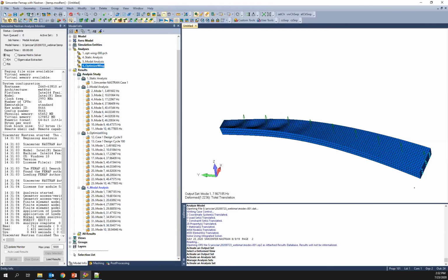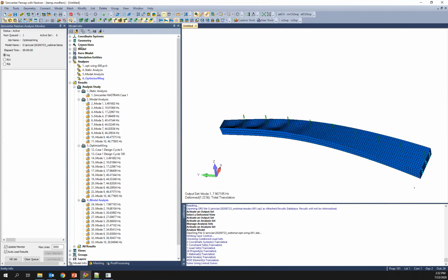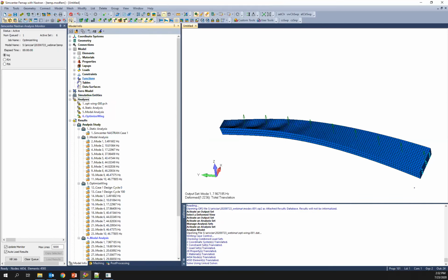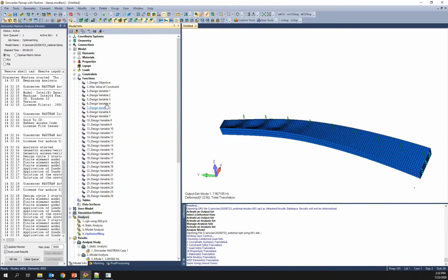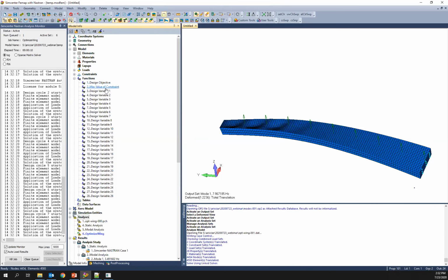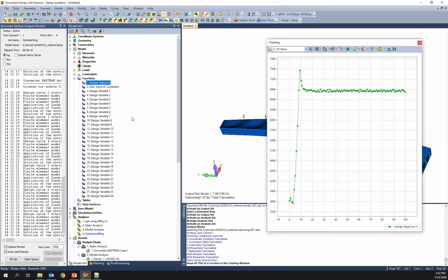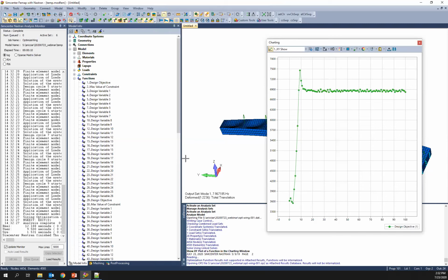And we'll run it again. Oh, and the other thing is, normally we would check convergence. I didn't open the F06 and do what I normally would in this case, but we have the same information that we talked about for the beam problem, where we can look at the design objective history, and we see we actually had to increase the weight of this wing to satisfy those constraints for that first run.